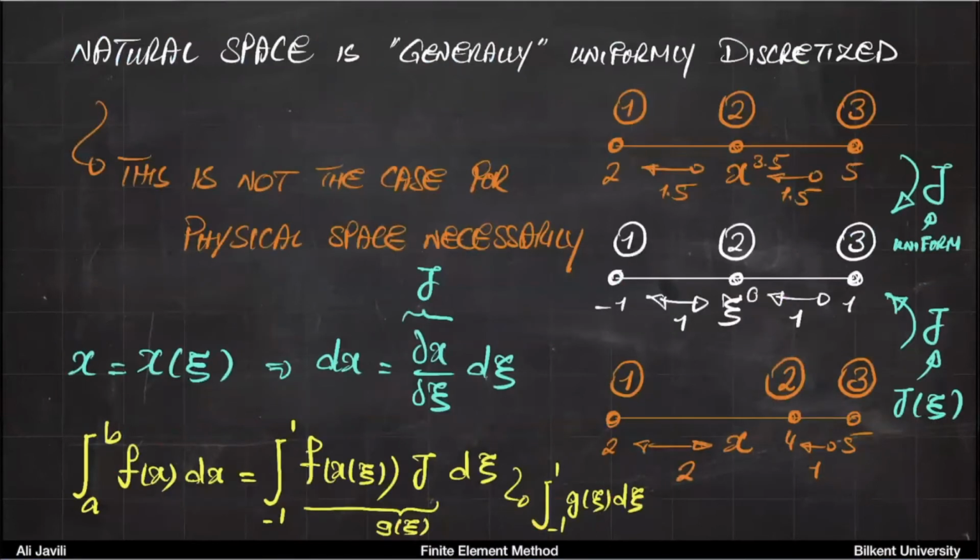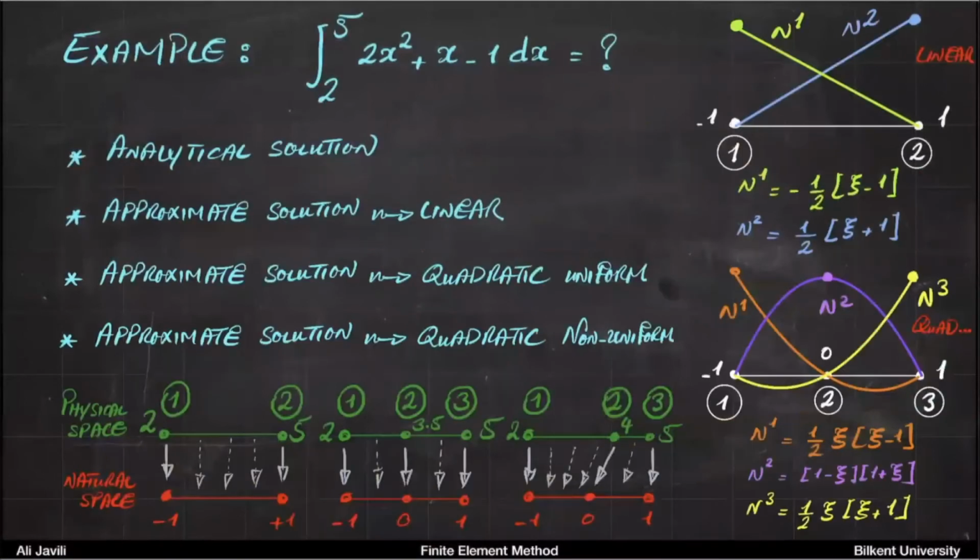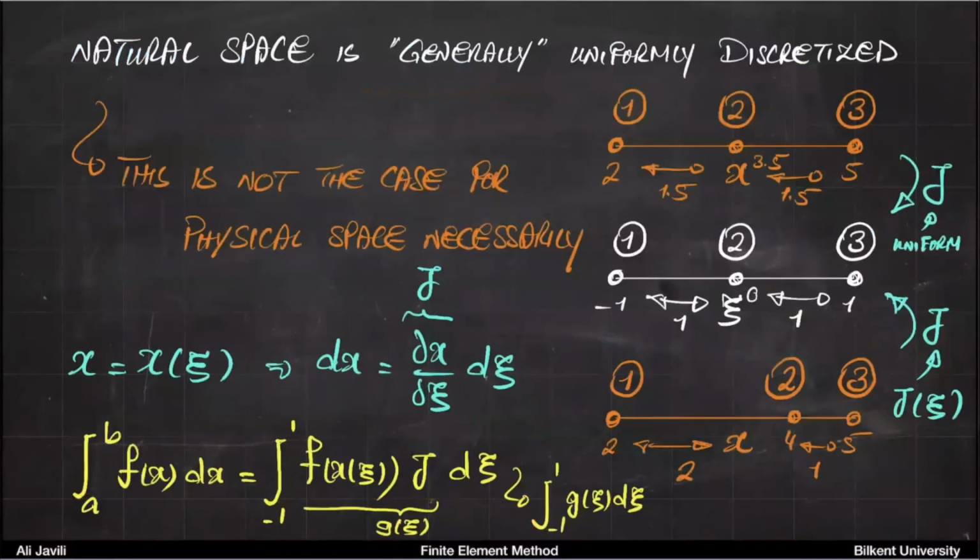You need to calculate this. And based on the order of this one, you need to calculate the number of Gauss points. Okay, so this is the key. Does that make sense? Now, there are 2 implications about this. One is this thing that I just told you, it almost never happens in practice. So you do not have this information that I just told you. So basically your best guess is to go with the order of this one. So if that is quadratic, you usually can go quadratic. I mean, on paper, we do one exercise together, but you don't have that insight into the problem usually.